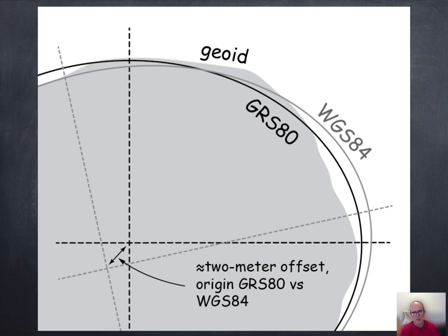and then when we want to bring in data from the ITRF WGS84, we'll calculate the mathematical formulas that allow us to do that without injecting any error. So there's an offset of about 2 meters, 2.2 meters, between the mass center and the geometric center origin. But we just went ahead and used our old one in the US to not confuse and make a lot of mistakes for the surveying.